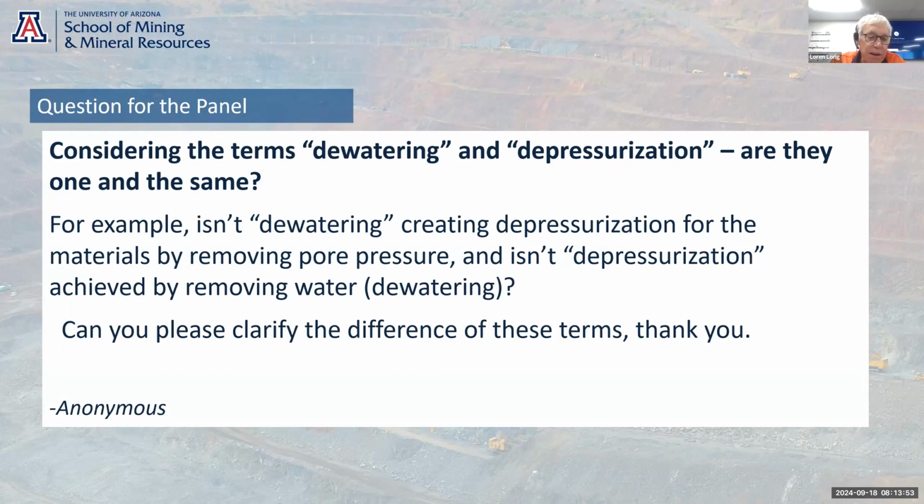So I was just going to add one wrinkle to this. Agree with what Jeremy said, and dewatering, depressurization normally are associated with water in the rock or soil mass. I had a boss who told me that when you pump out from a sump, then that was not water inside the rock or soil, that was termed unwatering. I don't see that anyplace else. Maybe that was just his term, but it's probably useful to have a separate category for that as well. And if you want to use it, go ahead.